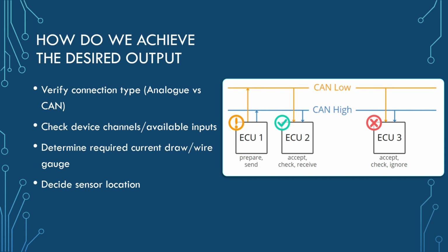CAN bus is usually preferred in automotive, but it does have a saturation point. It is 1 megabit, so it is a lot to get there, but we don't want to pile everything on the CAN and risk getting to that saturation point, especially when you have an ECU with a lot of analog channel inputs, so it's fine to feed that data directly through those signals. Most of the sensors that do go on CAN are temperature related sensors, just because of how the gradient works between them. It's easier to put them on the CAN system, and pressure as well sometimes.